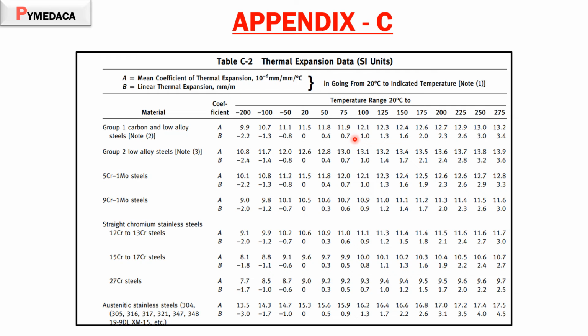You understand, 7 mm is too big. If the line is going to expand 7 mm, then whatever comes in front of it will break through, basically. So at 85 degrees Celsius, we can consider it 0.8 mm or 0.85 mm. Basically, if the line length is 10 meters, then it will expand around 8 mm to 8.5 mm.